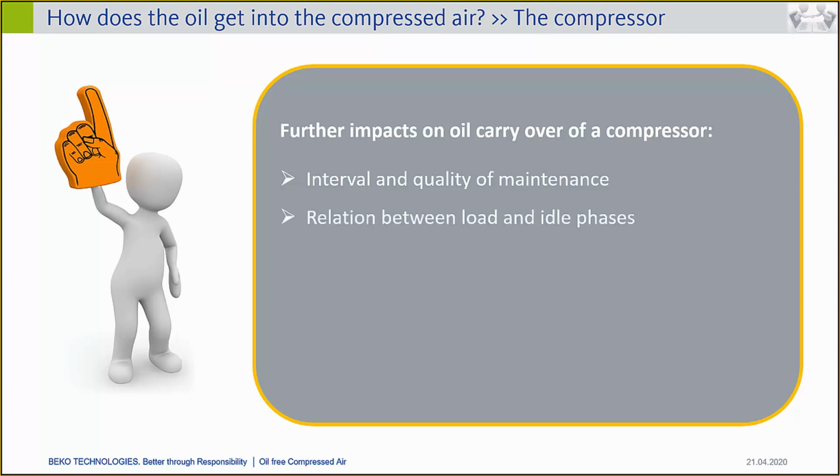Then one impact is the relation between load and idle phase. Particularly in a compressor station where multiple compressors are installed, the controller of these compressors needs to be programmed with a good setting. Otherwise, some of these compressors are in a long idle phase, for example. And in some cases, where the customer just has one compressor installed and has the VSD type for whatever reason, in many cases this VSD type also runs for too long in idle phase, and that also has a negative impact on the oil carryover.